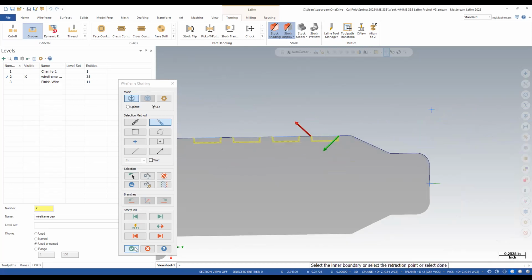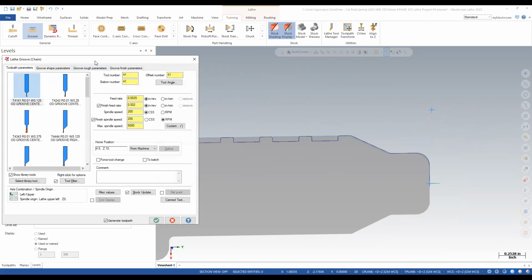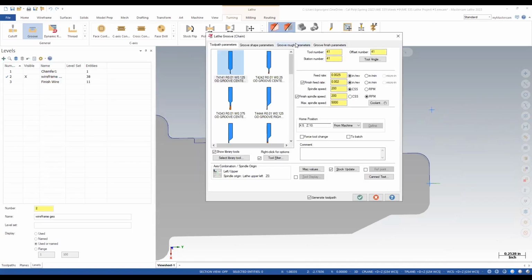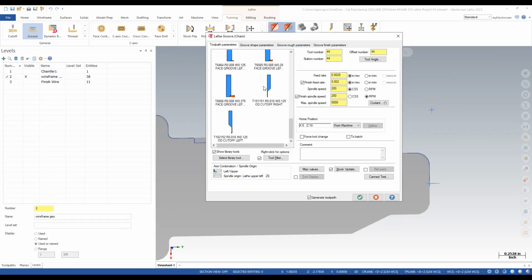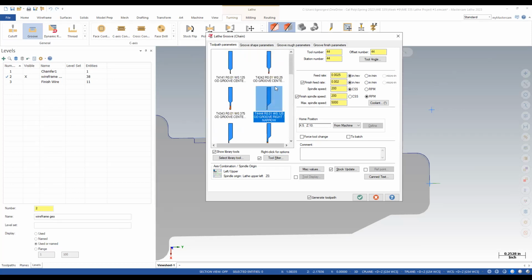So when I hit check mark, it doesn't matter what type of grooving tool you have here in terms of right, center, or left. You know why? It's going to go in and groove. It matters for simulation. If you want to make it so it's perfect, we have a right-handed grooving tool. So we're going to grab a right-hand grooving tool. In fact, is ours 125? On this sheet, it says it is, but no, what's the grooving tool? 0.095. The sheet's got it right.